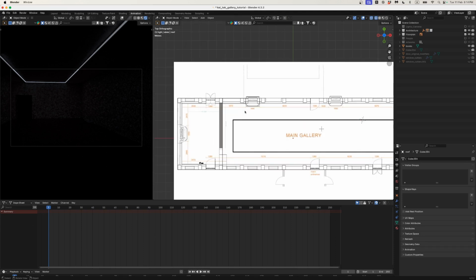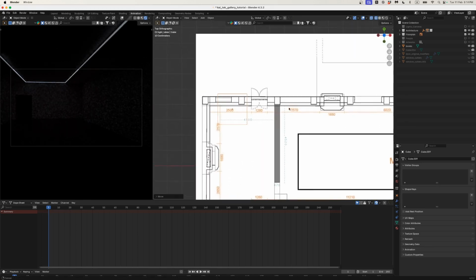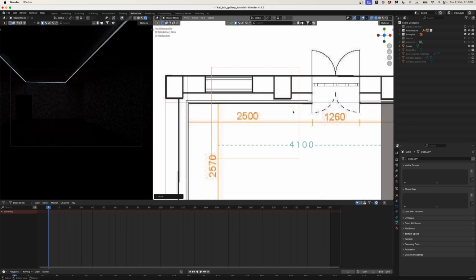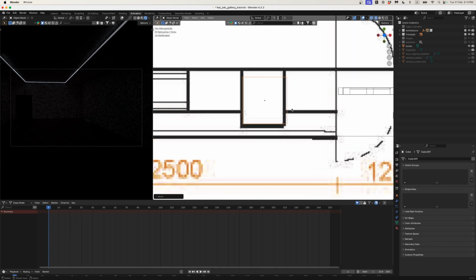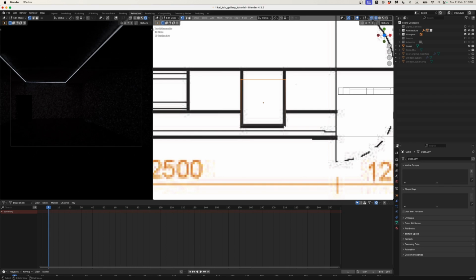So, okay, I'm going to make some new geometry here. I'm going to Shift A, add a cube, and there's that cube, and I'll start making one of these pillars. So I'll scale it down here, and just for argument's sake, I can make it the same width, but we're not going to see any of this.